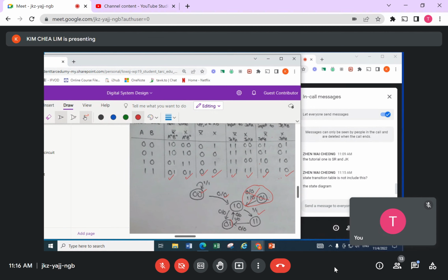You produce this state diagram, and you find that in these states here, if it's 1, they always loop, loop, loop, loop, isn't it? If it's 0, then only they can circulate or go to different states. What I'm trying to explain to you here is, if you see a diagram like this, usually this is a certain unused state. You are not using this state.